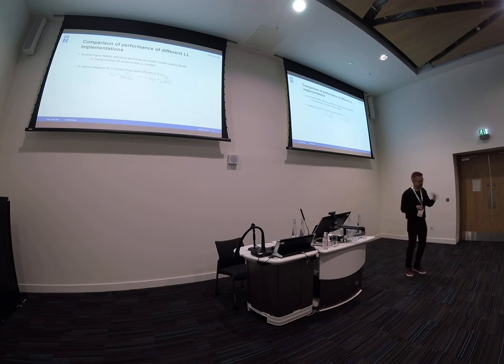And in order not to confuse myself, I'll be looking at comparisons of lift coefficient and not really drag, because if my lift is a little bit different, the drag varies a lot, because the drag varies with lift squared. Induced drag varies like that. So I'll be comparing lift coefficients of the different implementations and then the span efficiency, defined like this. And then I can see how the induced drag I get compares to lift, because otherwise I'm confusing myself.